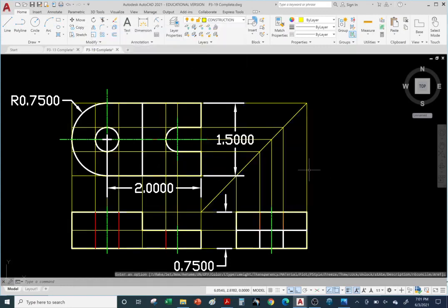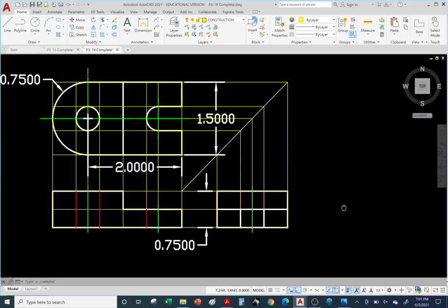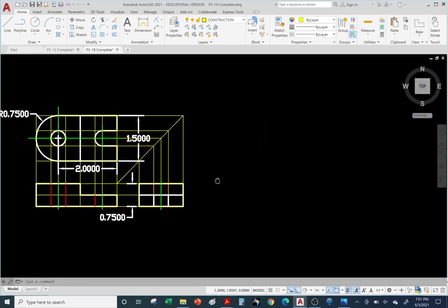And let's start by drawing our box. Okay, so our box will be 0.75 in height, 1.5 in depth. This would be also in parentheses because that's double dimensioning with the 0.75. And the overall length is 2.75. All right, so